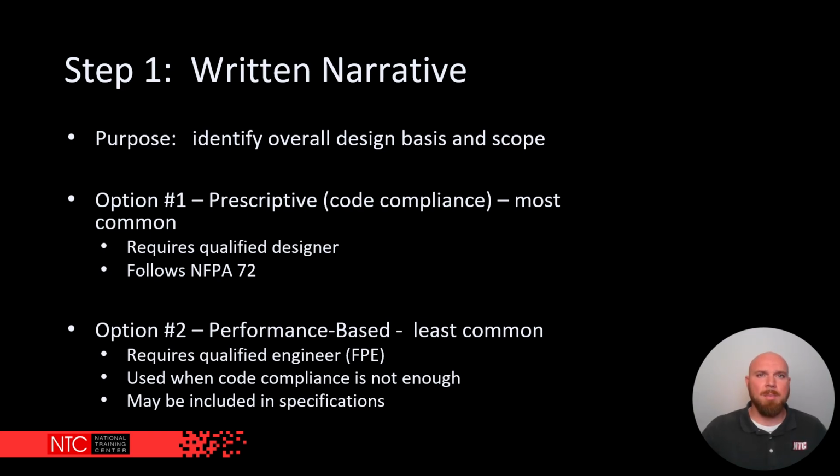This is the most common type of fire alarm design, requires a qualified designer, and all we're doing is following the codes, with NFPA 72 being the backbone of majority of what we're going to be looking at. Option number 2 is performance-based design, which is the least common type of design, requires a qualified engineer, an FPE. We use performance-based design when code compliance is not enough. A lot of times we see performance-based design as a specification for the job.